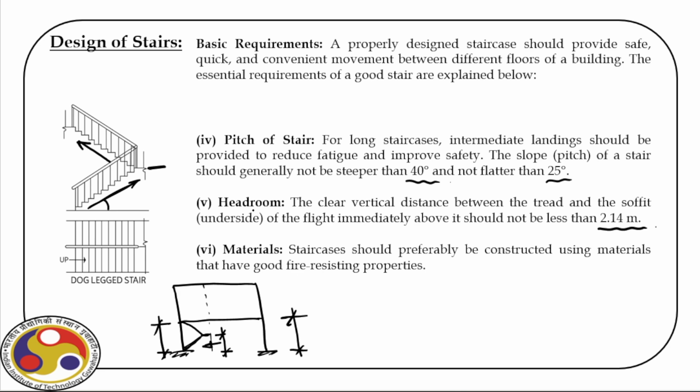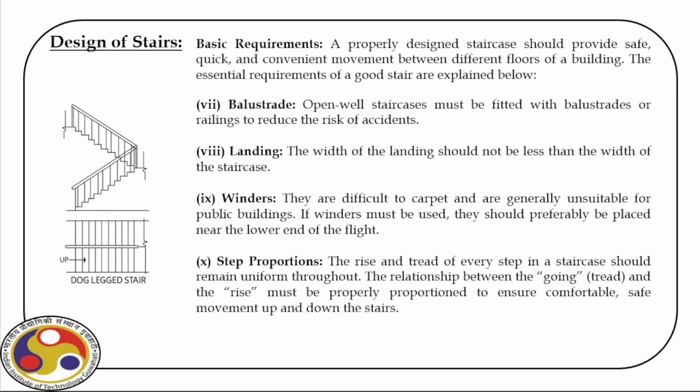So when we design that, we have to keep all these factors in mind. And then comes the material that we use for stair. In our case, we are going to use reinforced concrete. So we will have cement concrete plus steel rebars. With the help of those materials, we will design. But these stairs are extremely important during emergencies. So we should not use some additional materials. For example, you can see here we have railings, we have side panels for decorations. Those materials should not be inflammable, particularly during emergencies in case of fire. That may be risky, and that's why we should avoid using any such material.